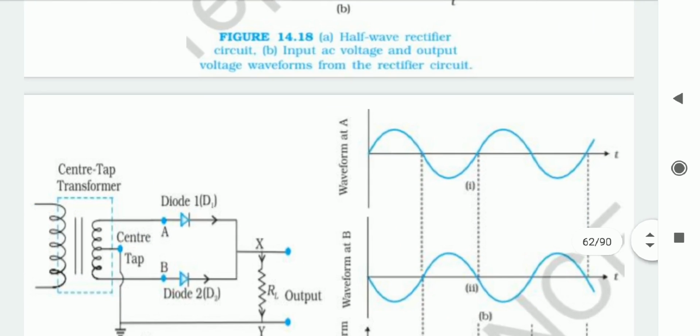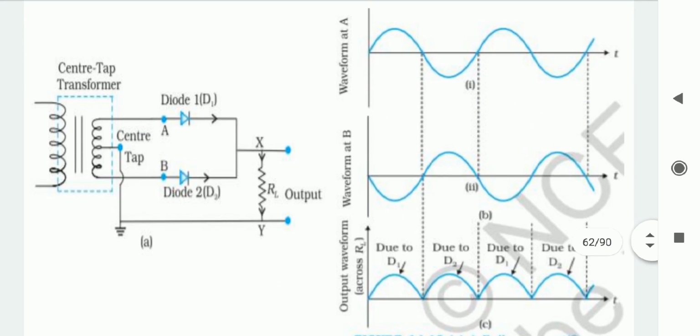As you can see in the diagram, the rectified output voltage is available during both the positive and negative half cycles, which is known as the full wave rectifier. The transformer's secondary winding has 3 terminals: positive, negative, and at the center, a terminal which can be defined as neutral.